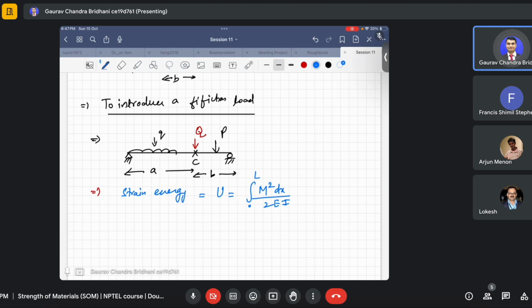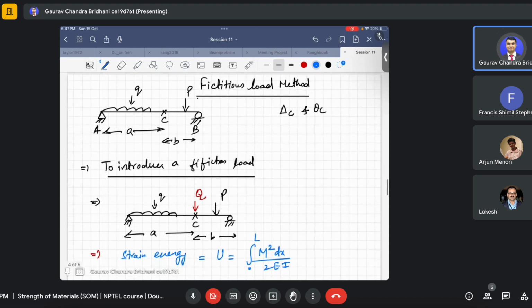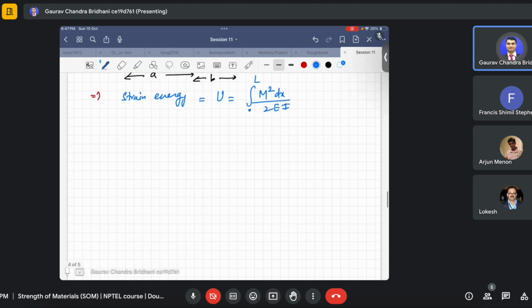Okay, as I told, the beam bending theory, or the Euler-Bernoulli beam theory, was developed for constant bending moment, that is, shear force is 0. However, in all the problems we solve, like this problem, does it have zero shear force along the beam? No, it doesn't. That means the beam bending theory can be used even for those cases where the relation between bending moment and stress is not the same. Okay, so we use it there.